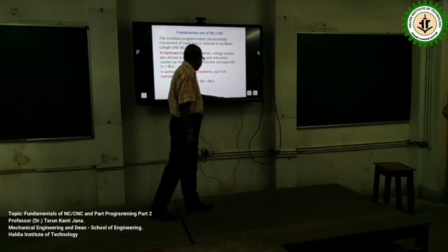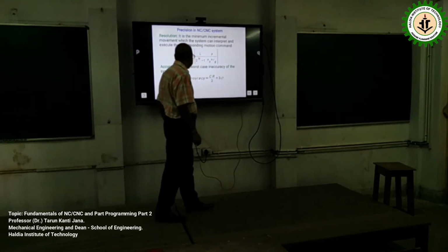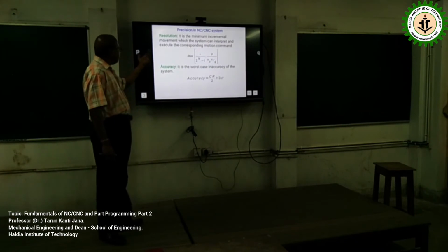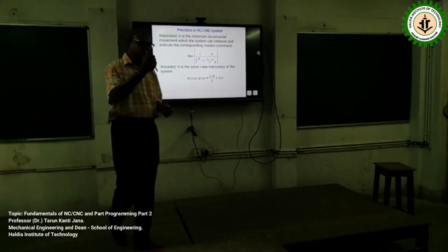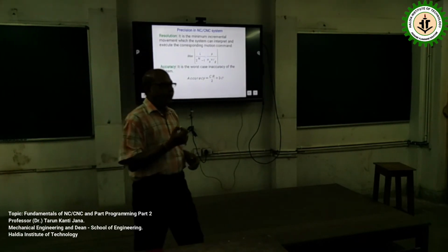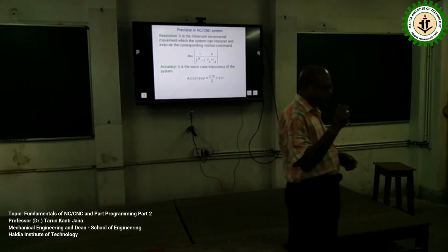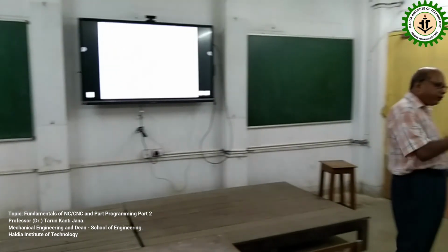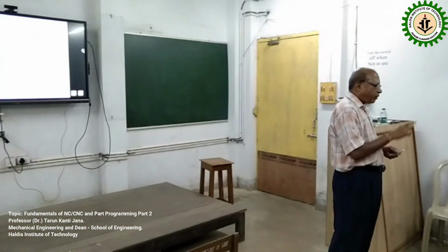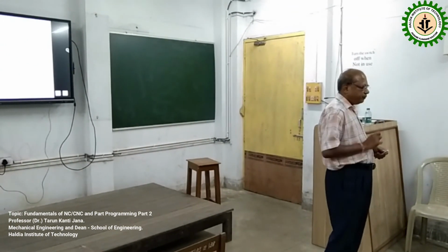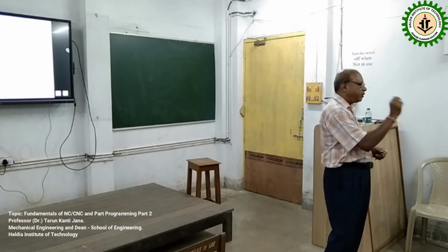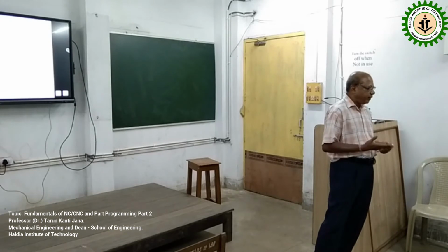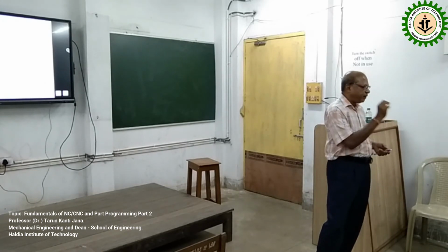These are not going to that part. That is the calculation part. One thing is the resolution, that is, the minimum incremental movement that is possible. Suppose I specify 40.8, but your requirement is much more precise, 40.802. Whether that particular machine will be able to accept such an increment, which is much finer and more accurate.